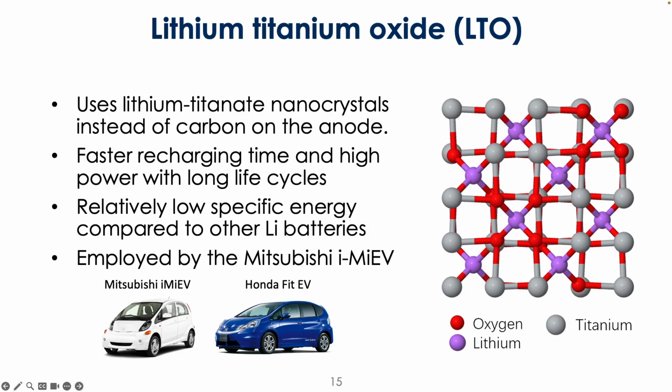Another fairly rare one is lithium titanium oxide. So almost all lithium batteries have carbon anodes, and this particular chemistry uses titanium nanocrystals instead. It's a sort of interesting concept, but tends to be a little bit more expensive. They can recharge faster. They have high power with long life cycles, but still relatively low specific energy, right? Without that cobalt.